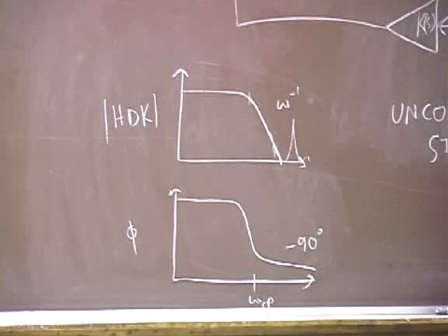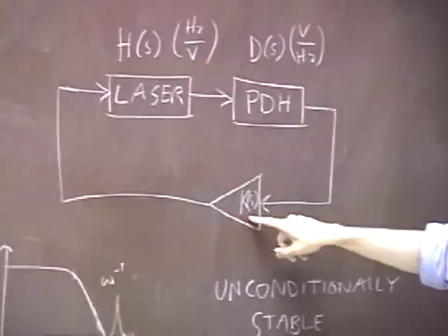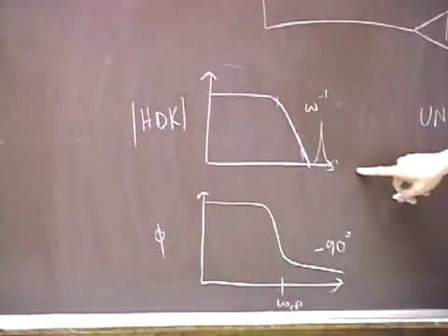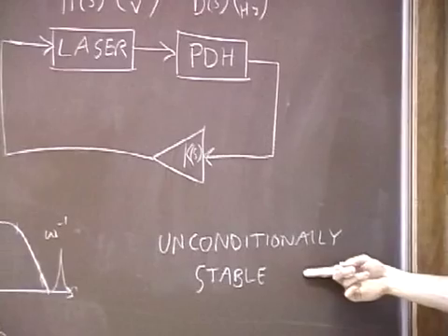So in real life, what we do is we introduce a pole in our amplifier at fairly low frequencies, low enough that we suppress all of the gunk that happens at high frequencies, and then we come back and we produce another unconditionally stable servo on purpose.